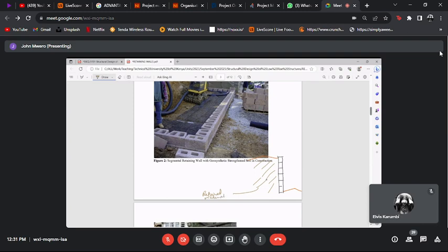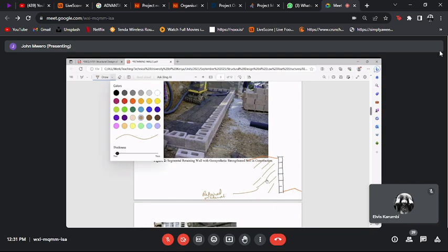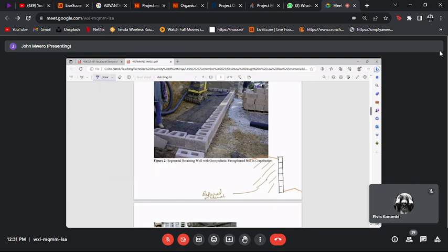So what you do is that you tie these blocks. They are tied back by some material, tied back into the retained material. So before you put the retained material, you put the block, you lay the tie back, and then you put the retained material and compact. Then you put the next block, you tie it, you put the material for tying it back, and you compact that layer. So it's done in layers like that, until you have your wall.